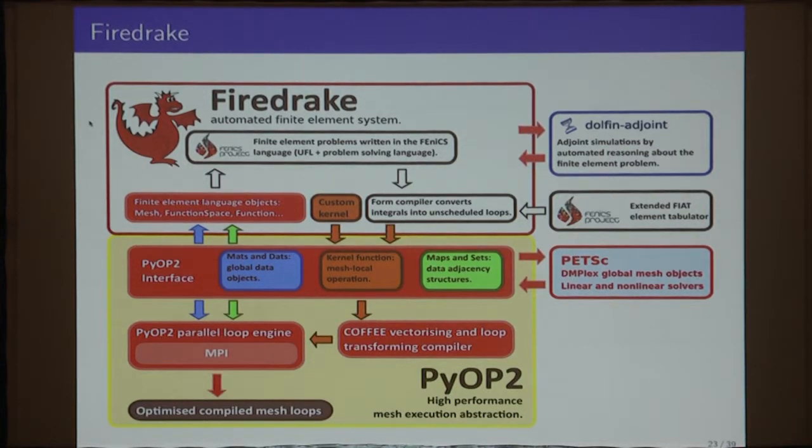And you specify, okay, this is the kind of preconditioning you should do in this system, and this is the type of solver. This is quite nice as well, because you can simply look up the literature, see what the preconditioner is, and what the best solver is for that particular problem. It's very elegant, a small amount of code. And then you apply the compiler. It generates the C++ code that's compiled. It runs and you get the answer.